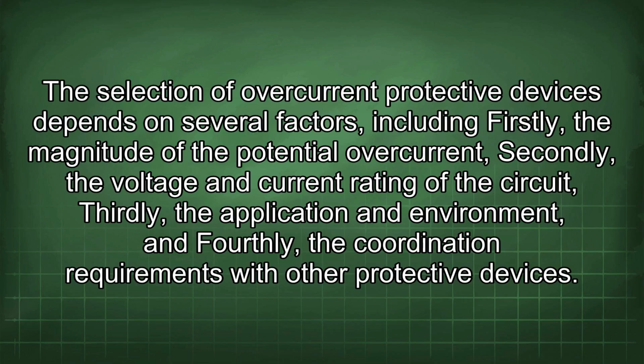The selection of overcurrent protective devices depends on several factors, including firstly, the magnitude of the potential overcurrent, secondly, the voltage and current rating of the circuit, thirdly, the application and environment, and fourthly, the coordination requirements with other protective devices.